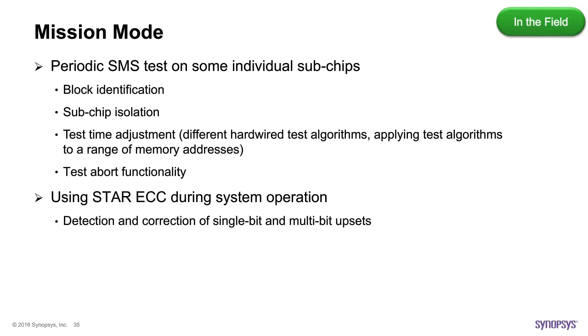In addition, now we do have these transient faults, and we need to protect against them. And this is not new. We have done transient fault protection for a long time. Soft errors are still there. Their impact is changing from time to time. And today we're seeing that the single bit impact that they used to create has changed to multi-bit upsets, where in the past the multi-bit upsets were a very small probability of what happens with soft errors. Today, almost half of what happens as impact of soft errors is in multi-bit upsets.